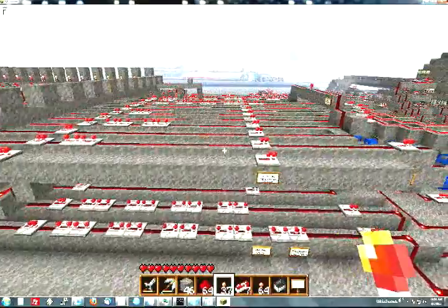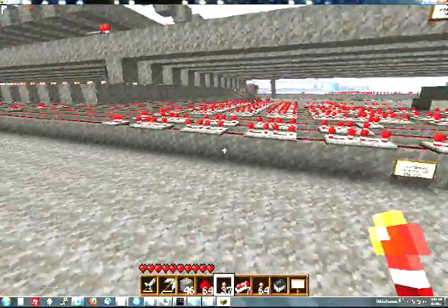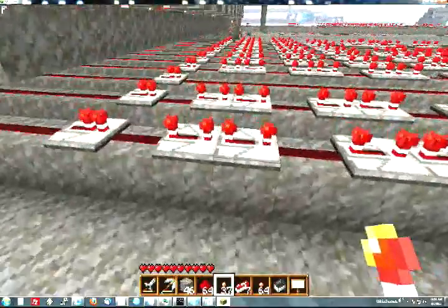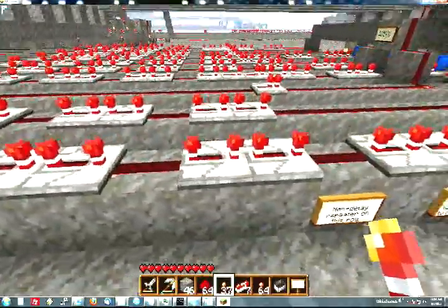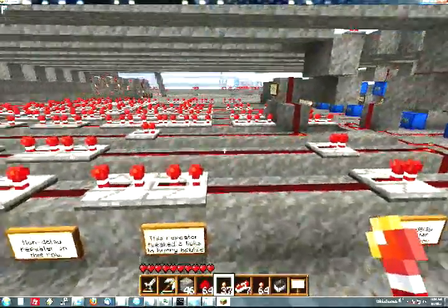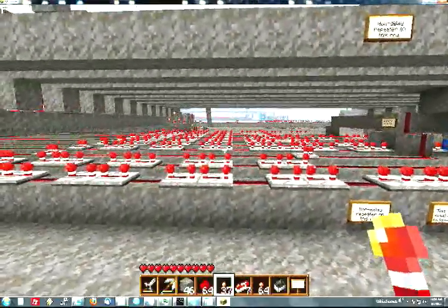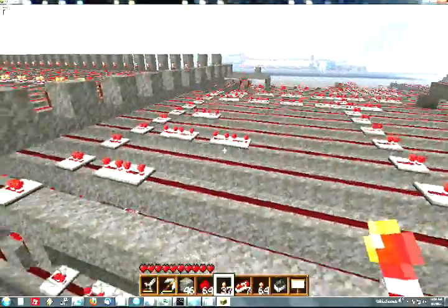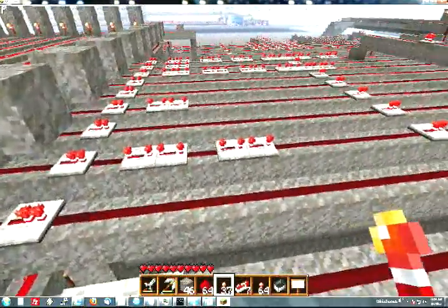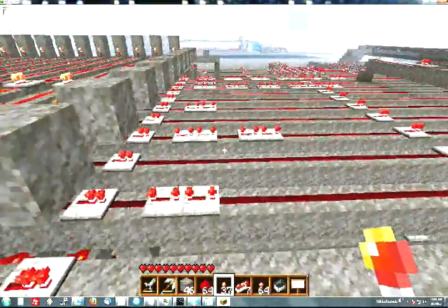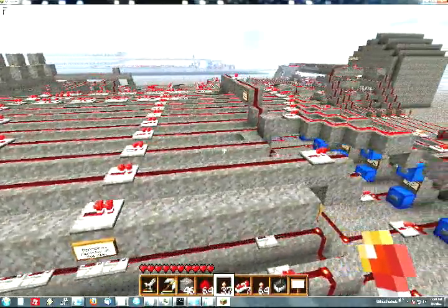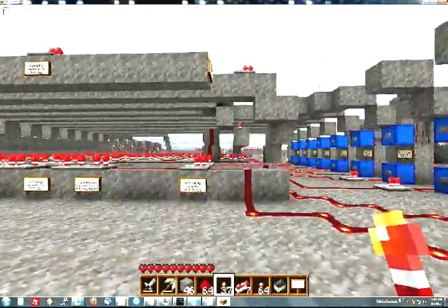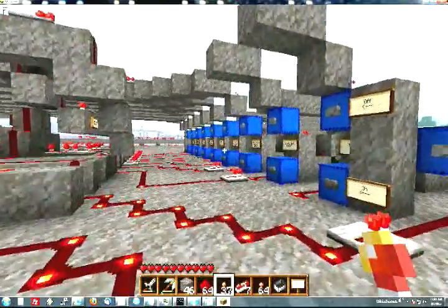And this is the time delay section. It ensures that each piston fires at the correct time. Each one falls within a certain quantization of time. So there are 8 different intervals that are possible for each piston to fall into, and each interval is about 8 ticks long.